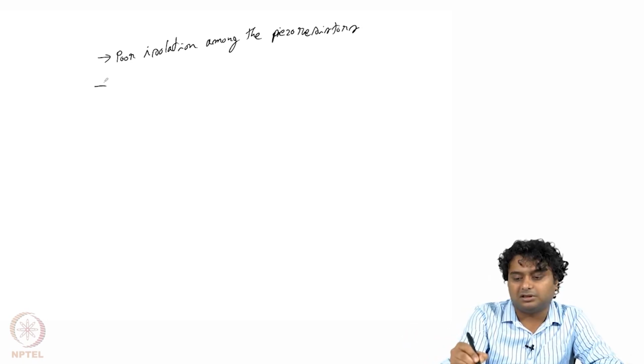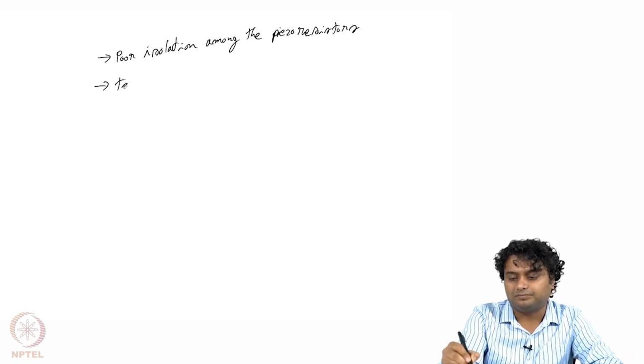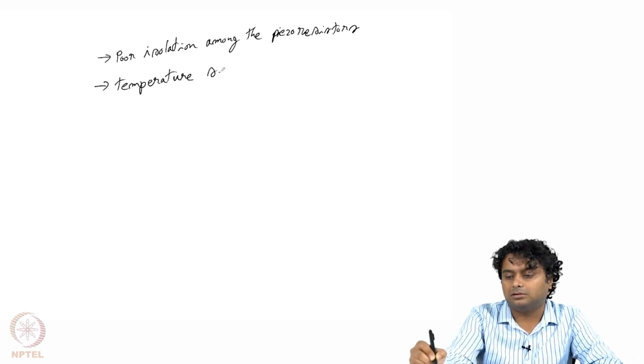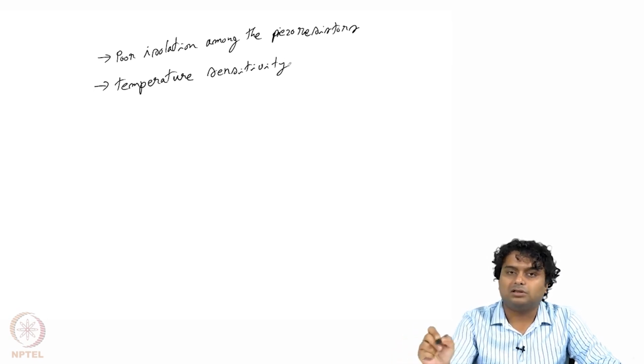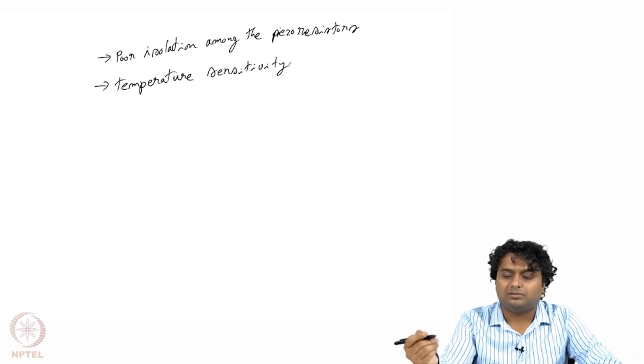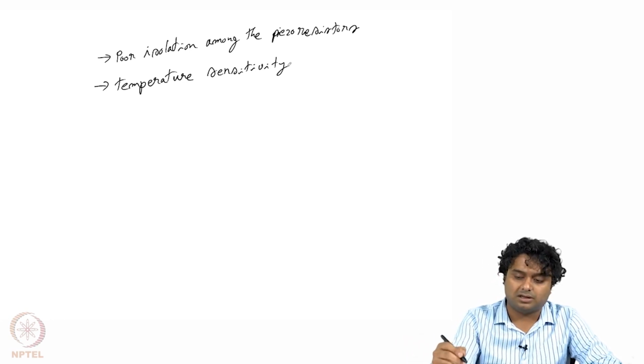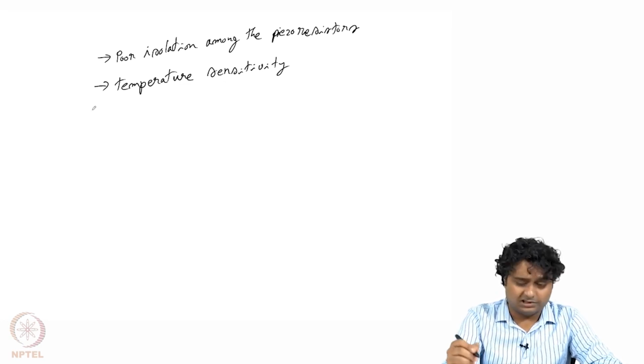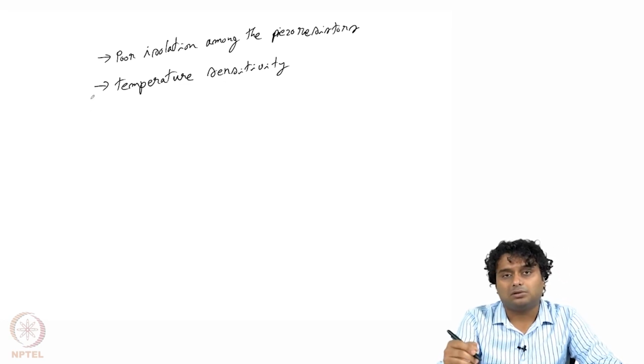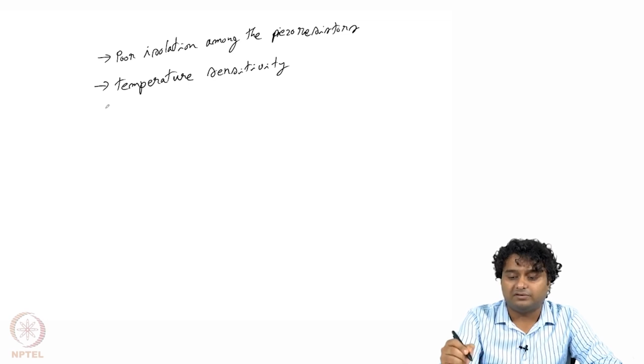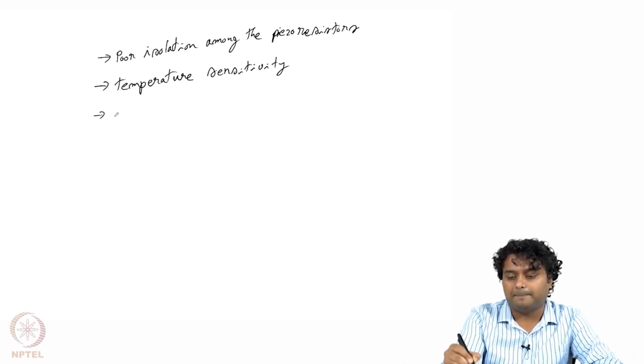Then temperature coefficient of sensitivity. So this nu, pi, all these factors actually depend on temperature also, and also the resistance itself, like resistivity etc., also depends on temperature. So this is another problem with this kind of piezo resistors. And most of the time we prefer p-type piezo resistors because they have a very good gauge factor, so the membrane needs to be n-type.